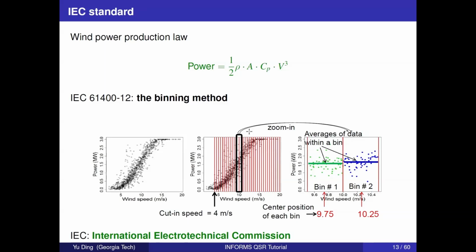So you're talking about this equation, right? In this equation, you have wind speed, but this wind speed does not consider the controller's capability to adjust the wind turbine. Right, so this formula doesn't have explicit wind direction. But it has an attack angle; or I should say, CP is a function of the attack angle. The attack angle is the relative direction of the wind versus the blade. So that's an attack angle.